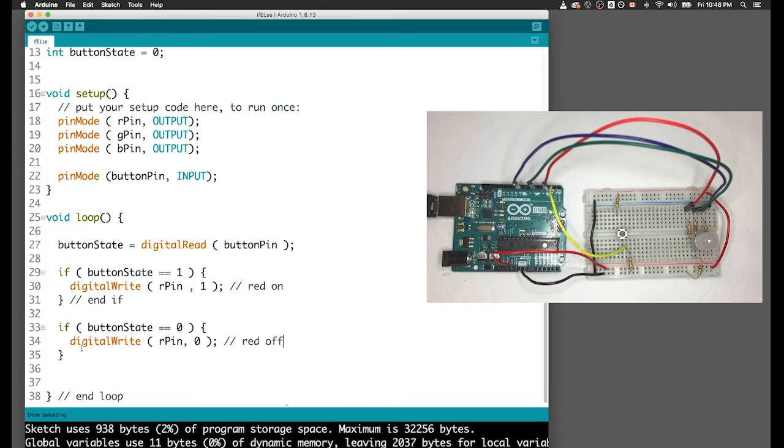We've seen that if we don't complete conditionals for the two different states of the button, so if we don't have an if statement for when it's on and when it's off, we might not get quite the behavior we're looking for. We have to remember that the conditional part of any if statement, so the if statement is combined with the if declaration, a conditional statement, button state equals 0, and there's different comparators. You can use equal to, greater than or equal to, less than or equal to, and one that's not obvious, you can always say not equal to.